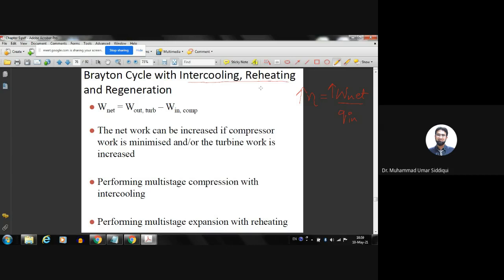The intercooler is going to cool the gas, reduce the temperature of the gas. So the gas volume is going to decrease, and then we enter this gas back into another compressor, and the rest of the compression is done from 4 bar to 10 bar. So we do intercooling in between. When you do intercooling in between, the amount of energy needed for compression reduces significantly. Okay, so this is one thing.